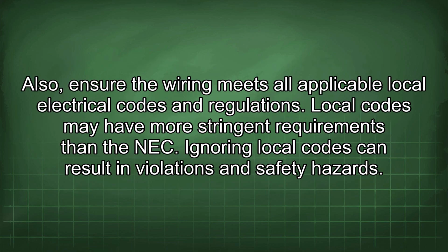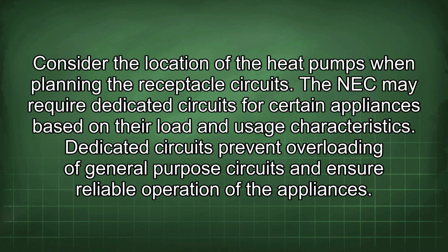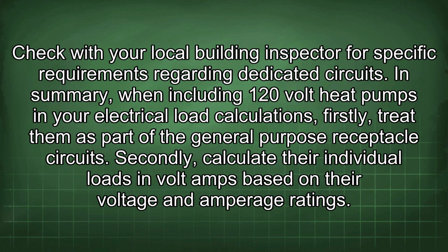Also, ensure the wiring meets all applicable local electrical codes and regulations. Local codes may have more stringent requirements than the NEC. Ignoring local codes can result in violations and safety hazards. Consider the location of the heat pumps when planning the receptacle circuits. The NEC may require dedicated circuits for certain appliances based on their load and usage characteristics. Dedicated circuits prevent overloading of general-purpose circuits and ensure reliable operation of the appliances. Check with your local building inspector for specific requirements regarding dedicated circuits.